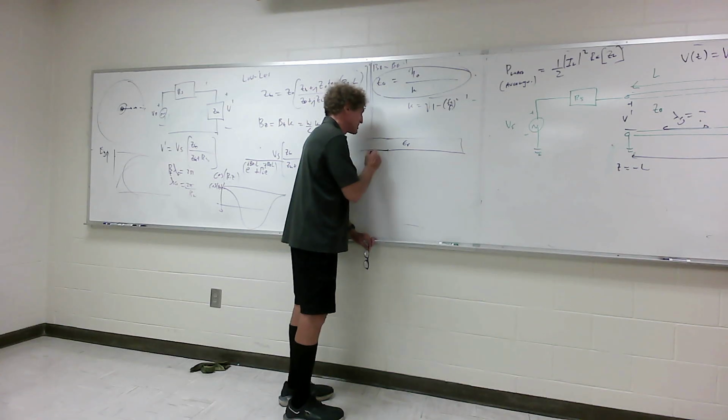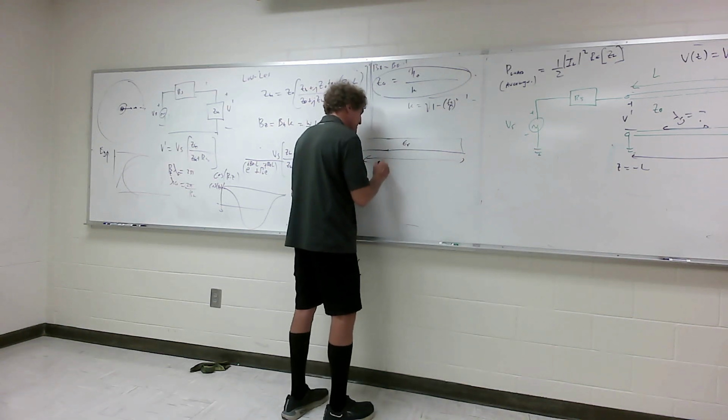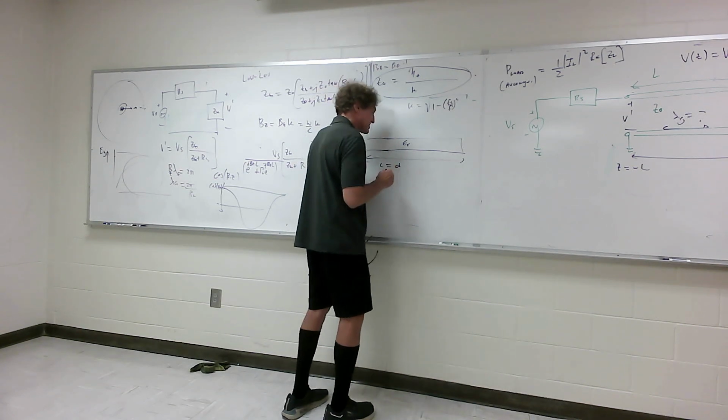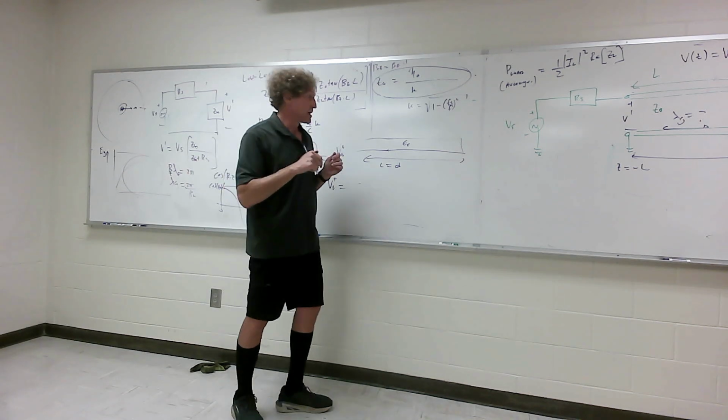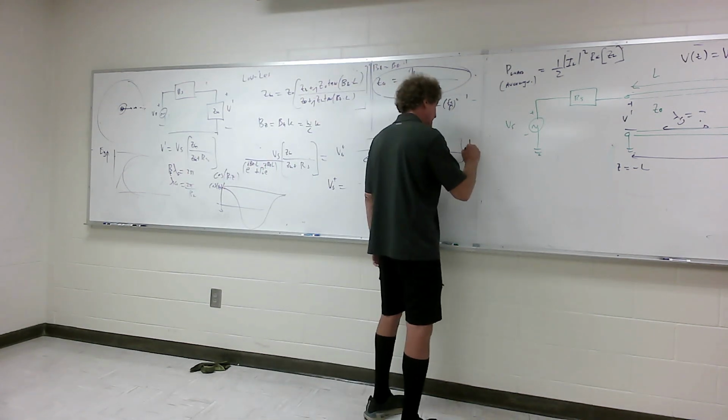So then in Wentworth's book, what he does is have a slab waveguide. A slab waveguide is really, there's no metal. It's a piece of dielectric. I'm going to go through this, not today, but I'm just going to show you. So they have a slab of material with some epsilon relative in it that's greater than 1. And what they really assume is the dimensions here are infinite. You might as well say that the separation distance here is infinite. So one dimension gets completely taken out of the equation. It's a slab. And there's another dimension here, A.